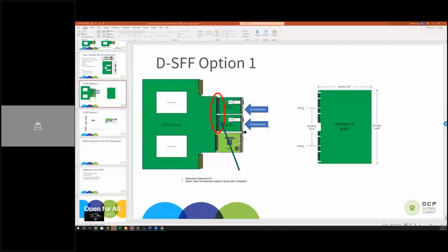One other question I have is whether or not you can have two different connectors, or whether the tolerances are such that, in order to locate the gold fingers within the connectors properly, it has to be a single long connector. And if so, is there any problem with creating such an item?